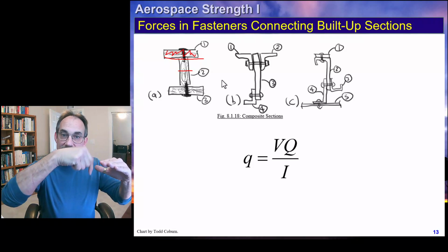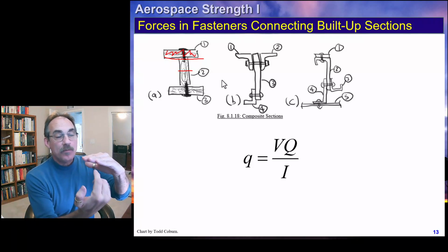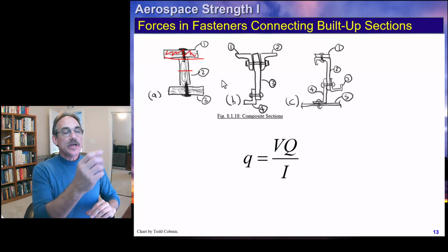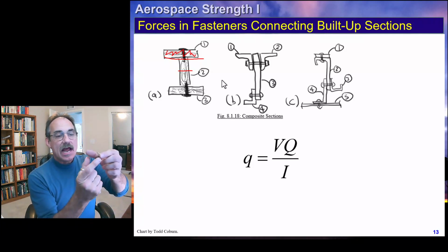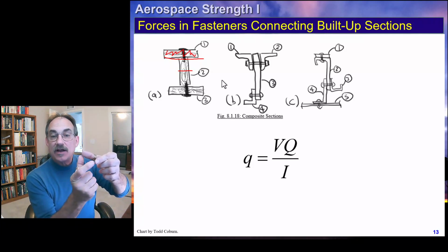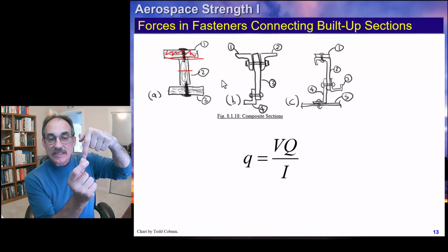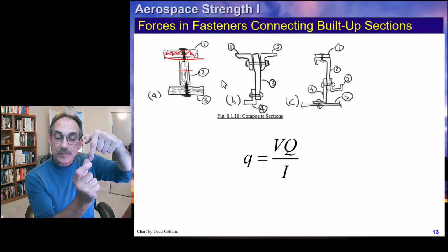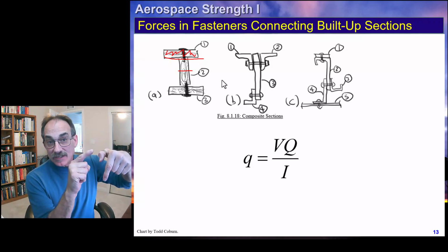Not only is it down the face of the section, but it's also coming out to meet that shear flow right through that cut. So if these nails are spaced at a certain spacing, then however much that shear flow is acting on that spacing, from, like, if the fastener is here and we have a spacing, that means half of that spacing acts from one side, half from the other side. So that shear flow times the total spacing is the total force on that fastener.